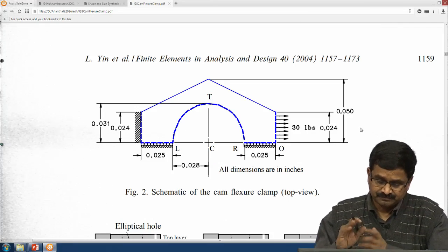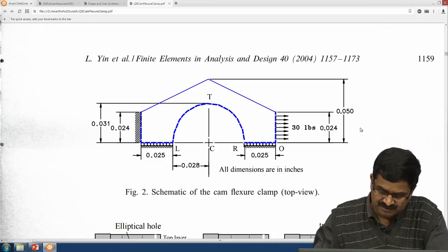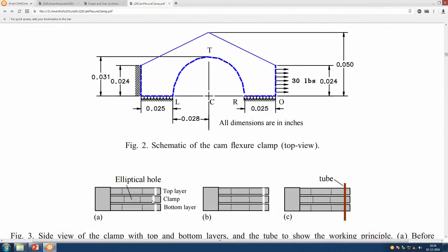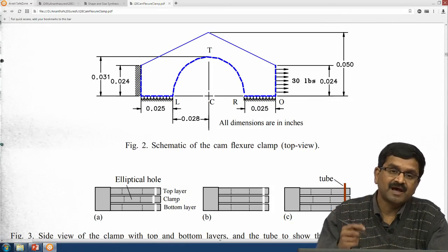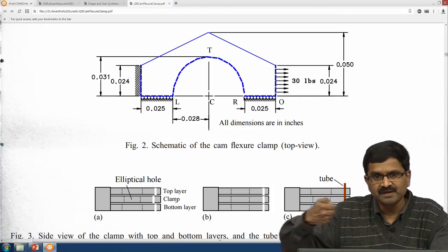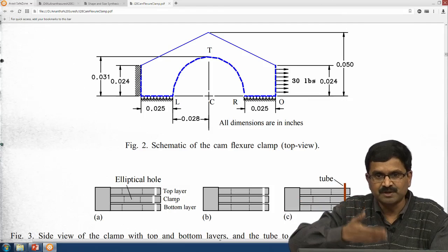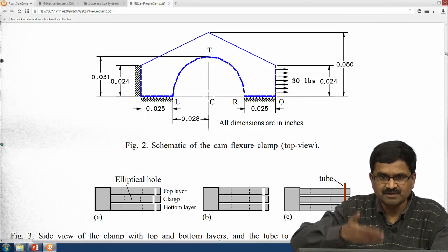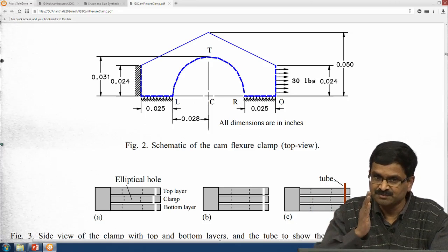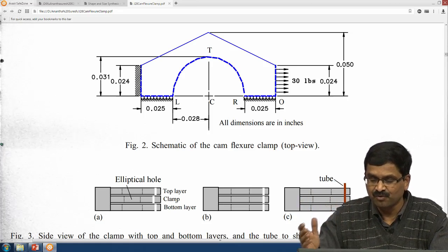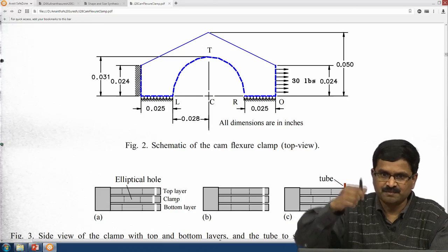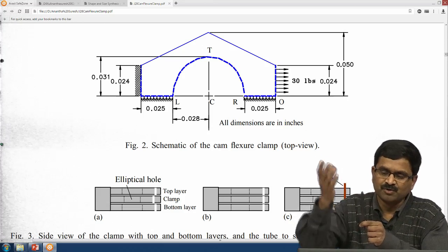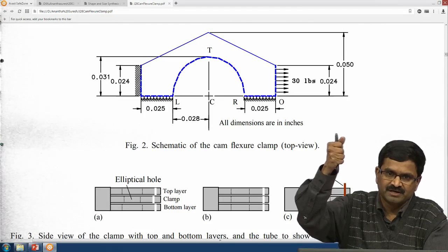Okay. Now, the idea here is that the misalignment that we see between these two, the larger it is, the better for them. Why is it better? If it is a large misalignment, when you apply a force and align it, when it tries to go back, if you think of the middle clamp layer as a spring, we are moving the spring by a large displacement. Let us assume a constant spring constant k. Then k times delta, how much misalignment you have covered, will be the force with which the tube will be held. When misaligned holes will insert the tube, much like this pen, when it wants to go back, now the tool is removed and the middle layer will hold it very tightly.